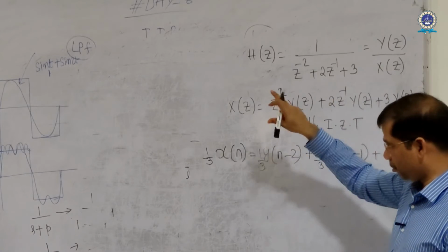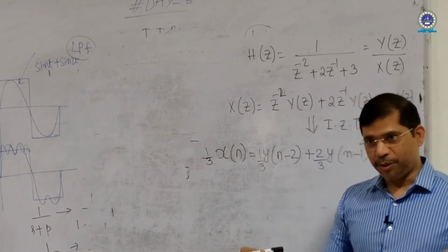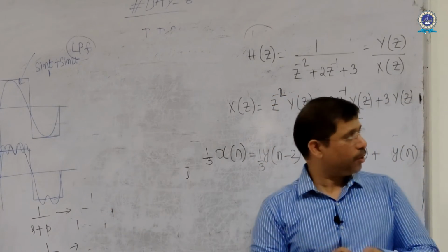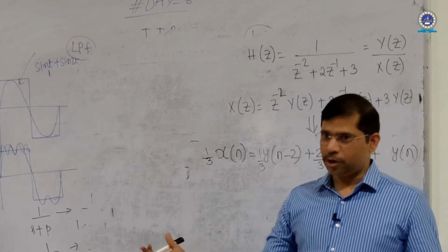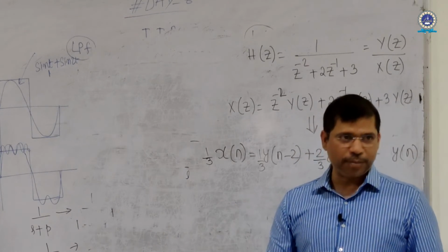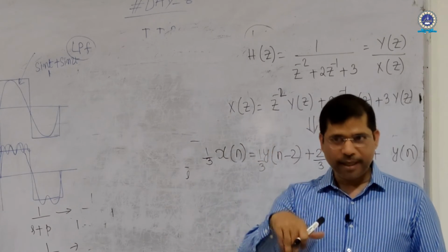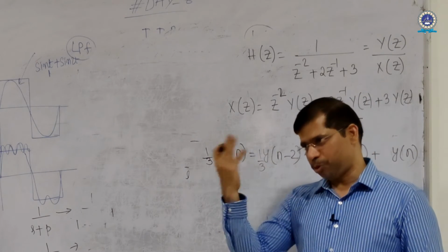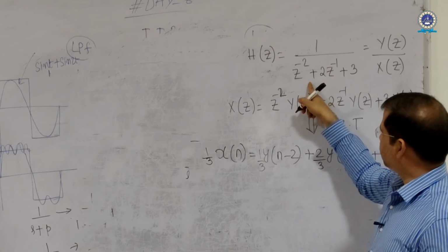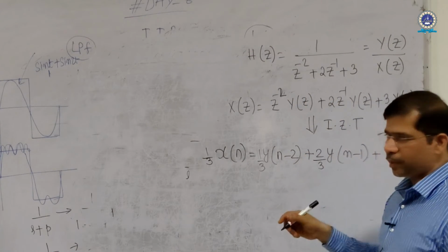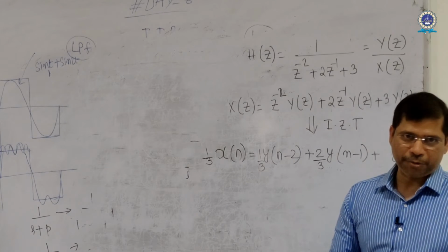If you teach Butterworth and Chebyshev design first, then you get very complex equations, and if you convert them into H of z, designing such equations will become much more complex. That's the reason I am taking a simple equation, and I can clearly explain the DF1 or DF2 technique.